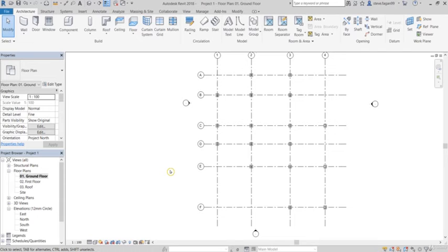So with the architectural columns, they're just a blank canvas. What that means is when we attach a wall to that architectural column, it takes on the properties of whatever wall abuts to it. So later on, we're going to draw our external wall around those columns. When we hit off it, it will automatically take on the properties. So it will turn into a block, plasterboard, brickwork, whatever we put to it. So it saves us time detailing around every single structural column in the project.